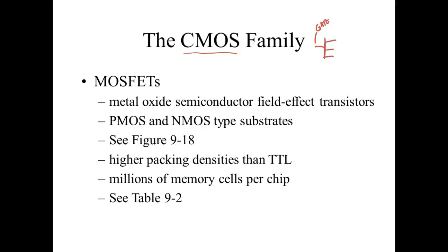But that's my static discharge. So when you start playing around with MOS, guys, you need to make sure you guard against static discharge, right? You understand? If you got a bag that's got it in there, you need to place the bag on whatever you're going to be working on. If you don't have a static wristband, then you need to constantly touch and make sure you're discharged against whatever you're working on. These guys right here are not very expensive.